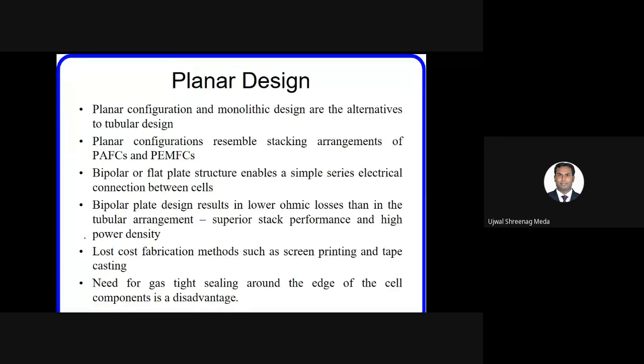So if you remember, in the case of tubular design, one of the disadvantages was low power density, which can be overcome when the planar design is used. And low cost fabrication techniques such as screen printing and tape casting can be used when it comes to fabrication of planar SOFCs.